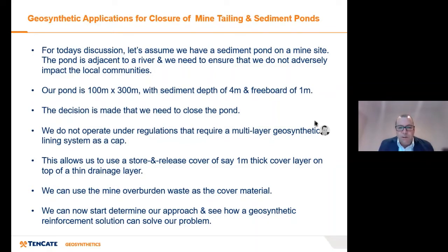The sediment depth is 4 metres, and then the freeboard, that is from the height of the water level to the top of the dam bank, is 1 metre. So the decision has been made that we need to close the pond. We don't operate under any regulations that would mean that we have to line the cap, so we can use a 1 metre thick cover layer.